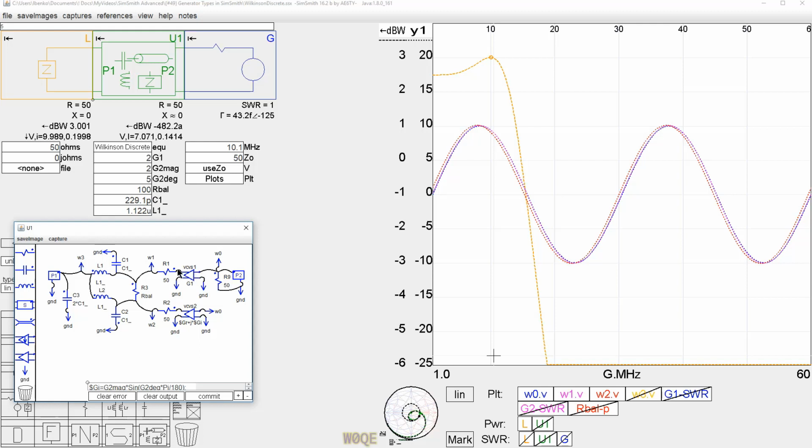infinite input impedance, 0 ohm output impedance. They're differential in, differential out. They have common mode rejection ratio that's perfect. They're mathematical, so they're perfect. So this generator generates a voltage. This generator, which is connected to the same point as the first one, generates another voltage.